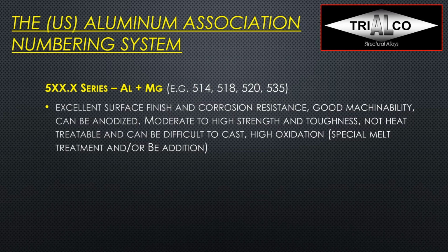that would be the go-to family in our foundry alloys, and you will get moderate to high strength and toughness, but pretty good ductility, even without any heat treatment, but it's pretty difficult to cast. You will get high oxidation because of the high magnesium, so prepare yourself for a special melt treatment and/or beryllium addition, which some people don't really like.